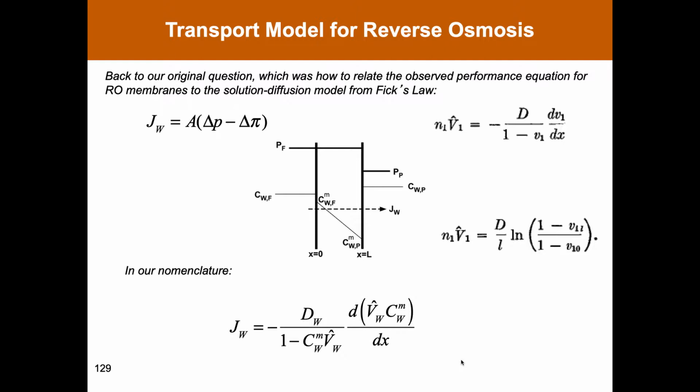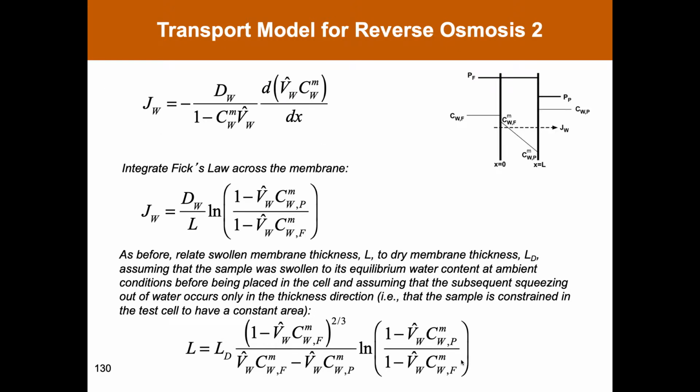These effects are typically unimportant when the solvent concentration in the membrane is below 10 or 20%. Nevertheless, we can start from this analysis and in the general sense write Fick's law, including these frame of reference effects as shown here. That expression can be integrated to get the flux of solvent in terms of the concentration